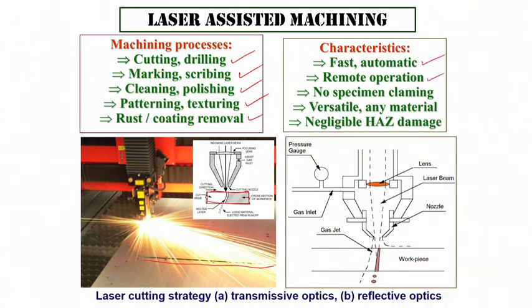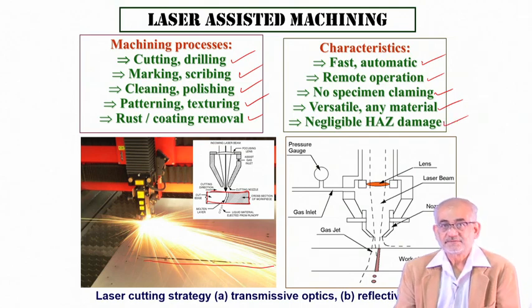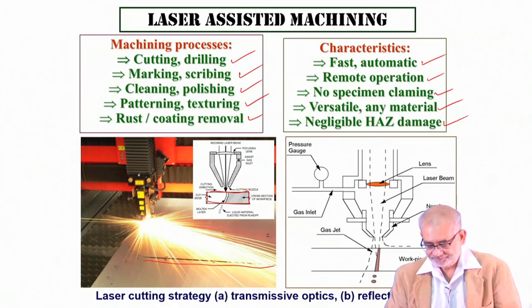The process is desirable because it's very fast and completely automated. There is no manual operation involved in particularly this kind of case. The specimen is not destroyed, and the wastage is minimal. Then it is very versatile, and practically any solid can be machined using laser, and there is very little or negligible amount of heat affected zone.